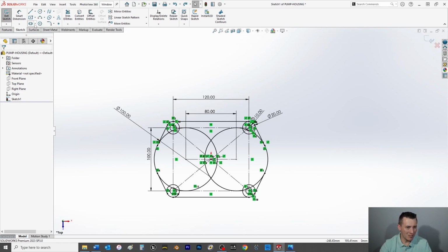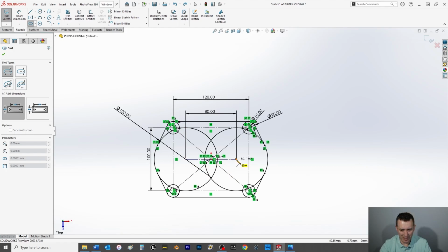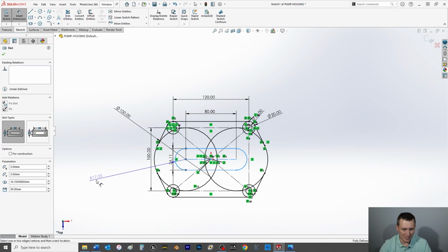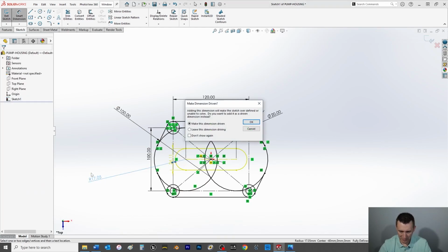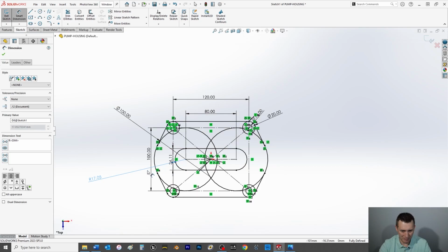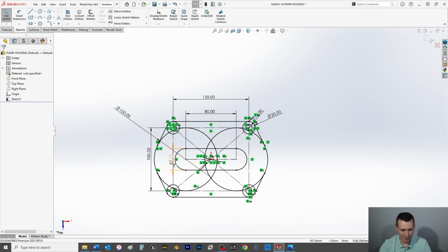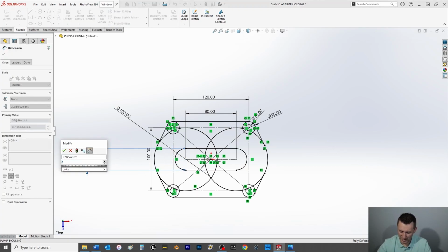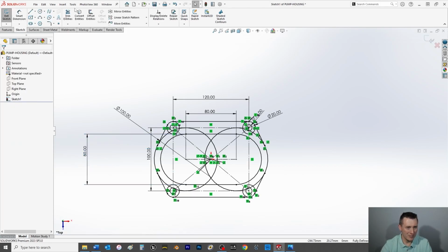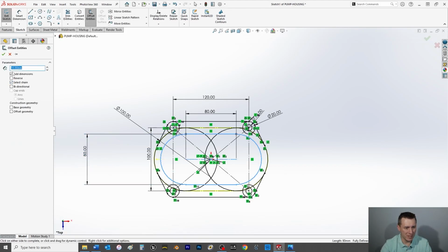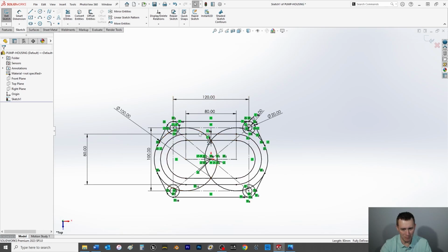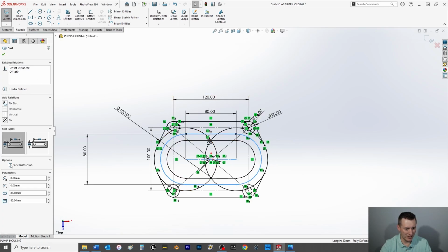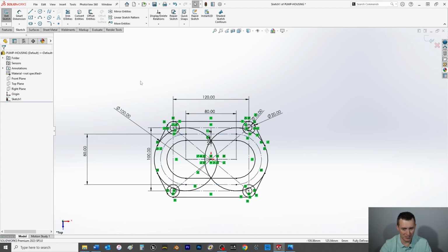Then what we're going to do also is create a slot here and here, drag out. This has a radius of, ooh, fighting me, are you? This auto-generated dimension here needs to be 80. Okay, then we need to do an offset on that same thing going inward. Reverse it. 10 mil, because the internal thickness of this part is 10 mil. And then we're going to take this and turn it into construction on this particular situation.